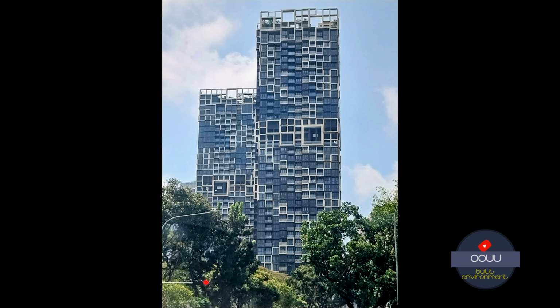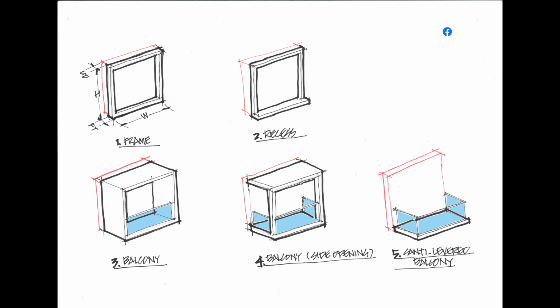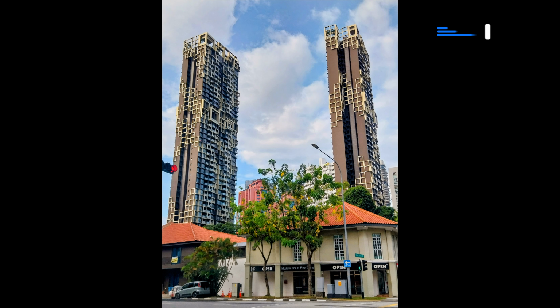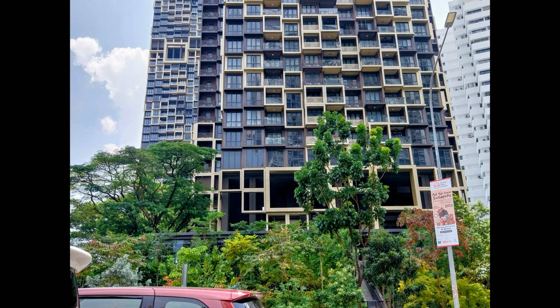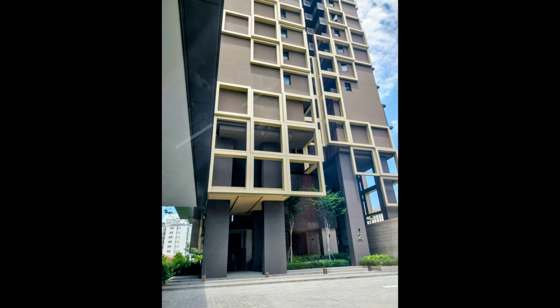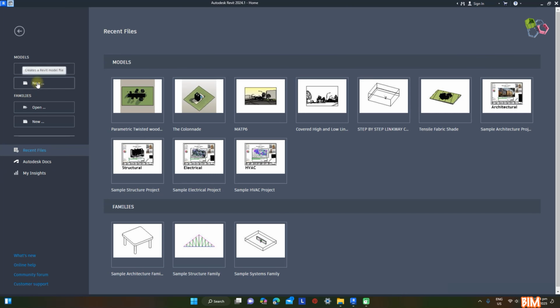Today, I'm excited to show you how to create these well-designed elegant residential towers using Autodesk Revit. I'll start from a simple curtain wall and gradually build up detailed facade elements like frames, balconies, and recesses. The actual towers are 40 stories tall, but for this demonstration, I'll model two towers at 25 stories, about 62.5% of the full height. This focus will be on using parametric families and curtain wall settings to efficiently create a realistic architectural model. Without further delay, let's get started with Autodesk Revit.